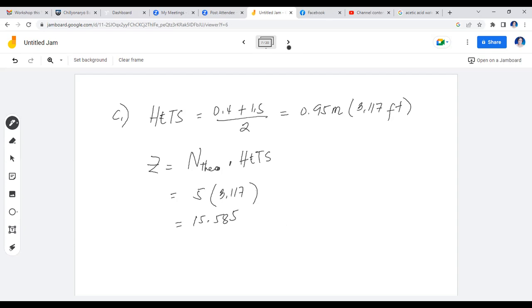15.585. But you don't answer this raw data, class, because in an extraction tower, you need to have allowances for the settling zones and for the inlet nozzles. So for your inlet nozzles, you have to give 2 feet for the allowance. For the settling zones, another 2 feet. And then this one based on the theoretical number of stages, so plus 15.585 feet.